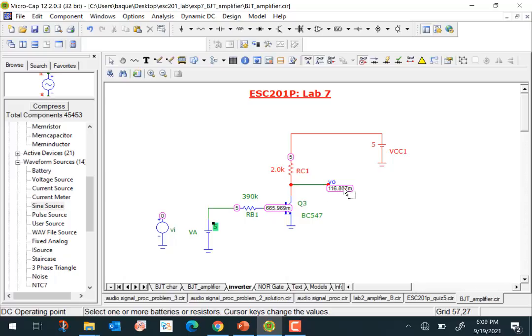The magnitude of this low voltage you could control by changing the value of RC or the value of RB. So for example, if I make it 3K, I can reduce the value further, to 98. So we can change all of that here. You can clearly see 0 gives high, and if you apply high voltage, you get a low voltage here.